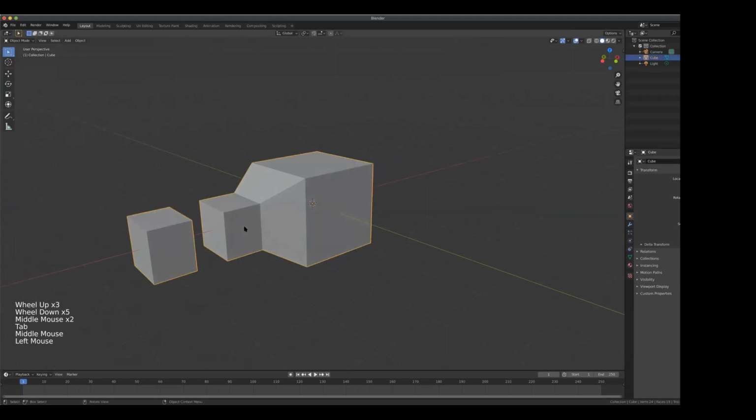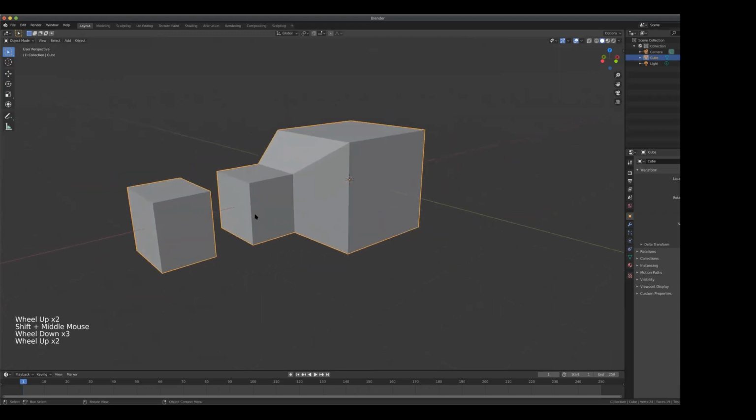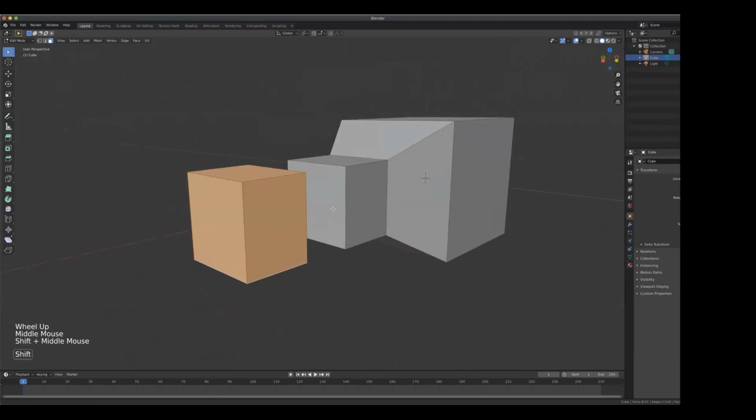So typically, in order for this to work, you need the object kind of joined together, okay? Because most problems I see with this with beginners is that they're trying to merge components with two separate objects. That's not going to happen. So you'd need to join the objects first. But since I duplicated this piece right here in edit mode, it automatically becomes part of this object. All right, so let's establish the points here and then connect them.